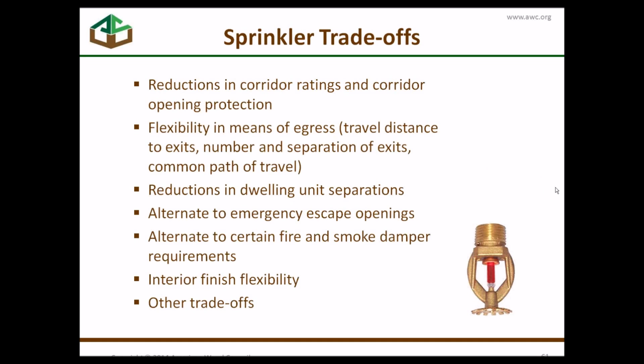There is a lot of active fire suppression, of course. Very effective, and it's superior in many ways to passive protection. Passive protection is also needed in many cases, but it always makes sense in a project to see what the total cost would be with sprinklers and without sprinklers, taking into account all the trade-offs that you get in the code. Many times it really makes it worth it. Certainly from a life safety standpoint, it's always worth it to have sprinklers in the building.